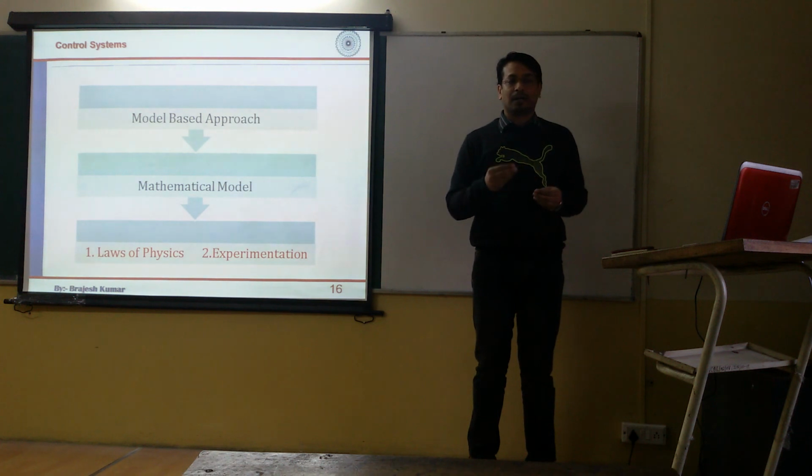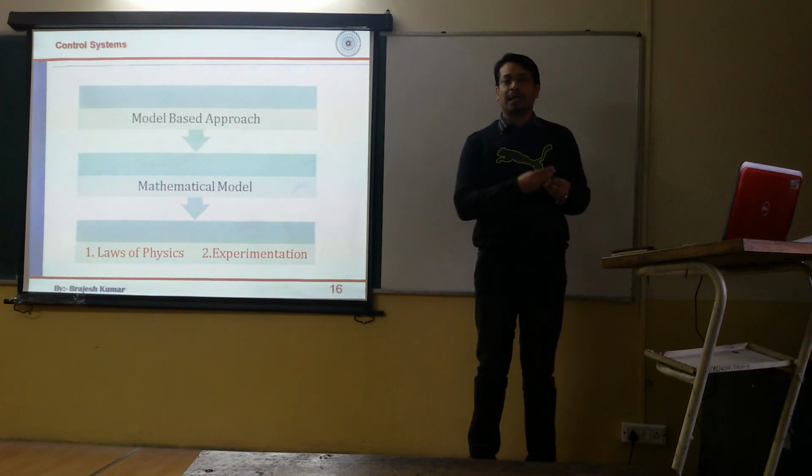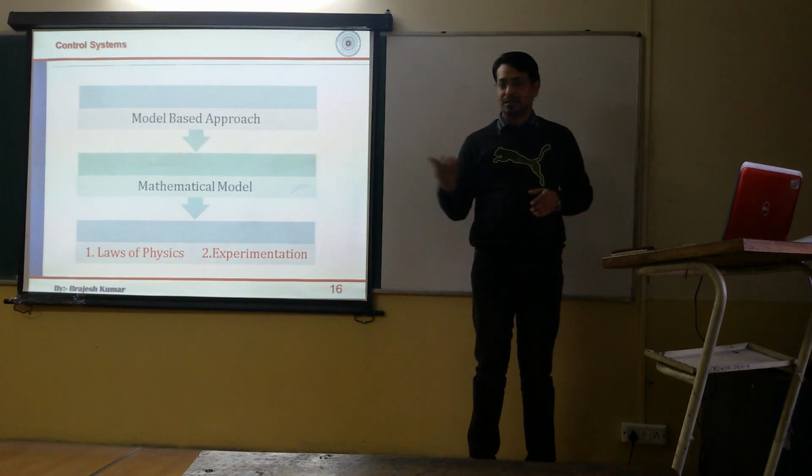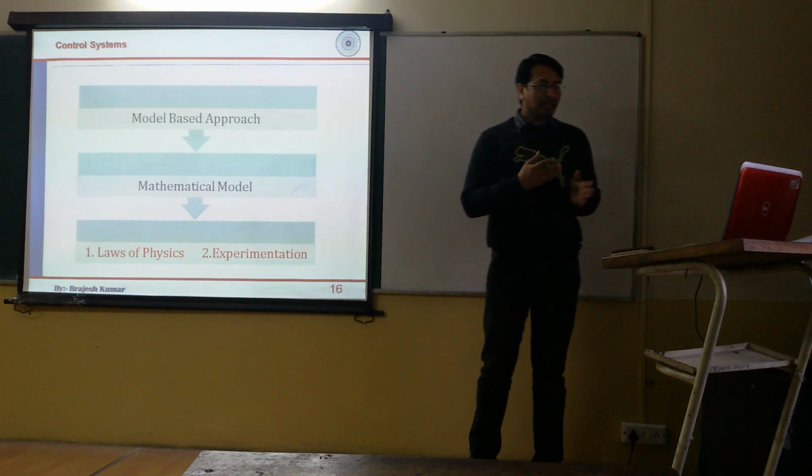First, suppose you have been given a system, you will apply the laws of physics. Based upon the laws of physics, you will write some differential equation. Then you will take the Laplace transform of that differential equation and define the transfer function. In the next session, you will see what the transfer function actually is.